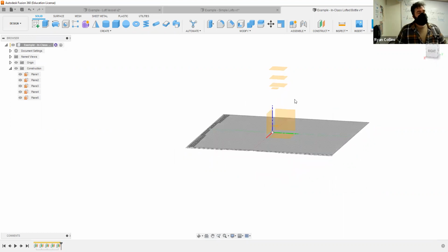That just helps lay out everything. If you want to work one plane, do a sketch, one plane, do a sketch, more power to you. I like to set up my construction planes based off of elevation dimensions, just as a good placeholder. Now, the other thing is, well, do I need construction planes? Couldn't I just make a sketch and move it into position?